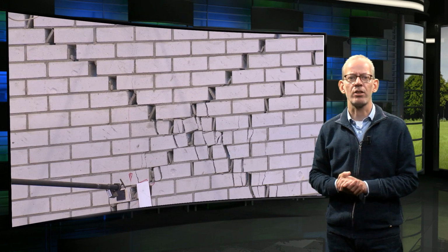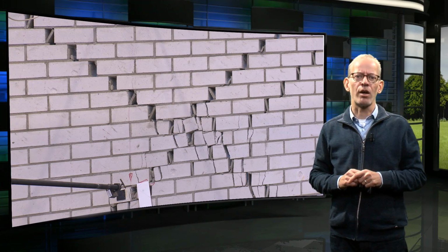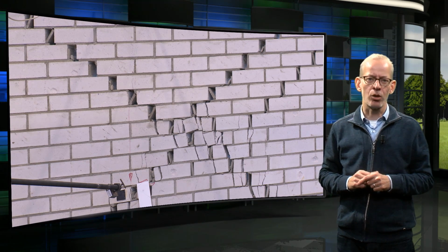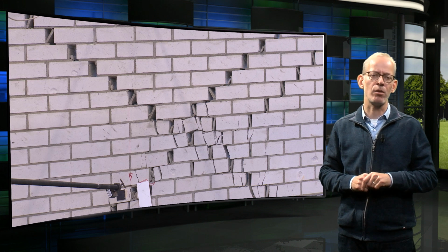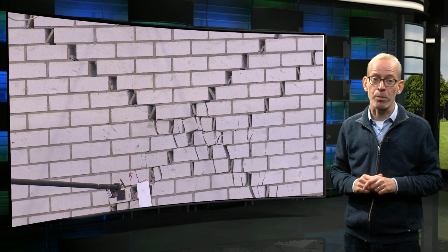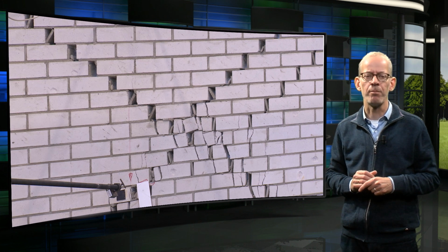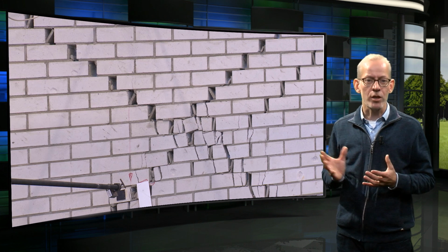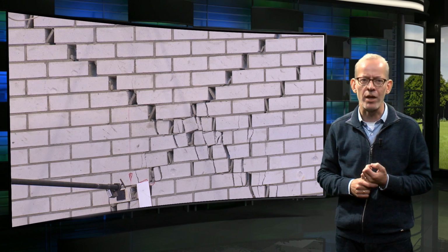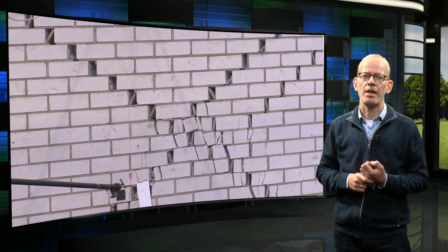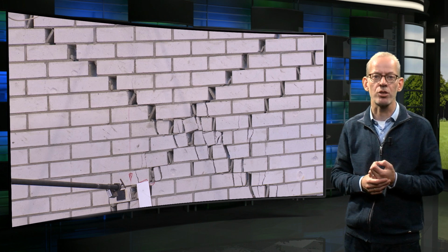Now let's have a look at a real experiment. Here you can see a detail of a wall after testing it. It was loaded in plane by a horizontal force similar to the one shown in the animation. This was an experiment at TU Delft during an experimental campaign for NAM. This masonry consists of calcium silicate bricks fixed with a traditional cement-based mortar. It is very similar to the type of masonry frequently used in Groninger houses.